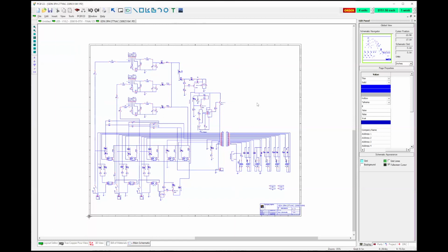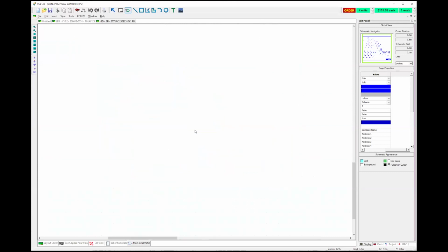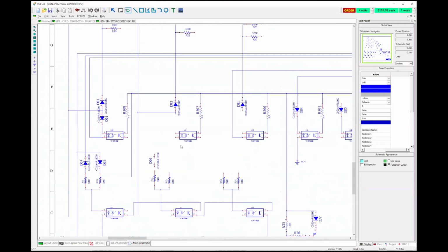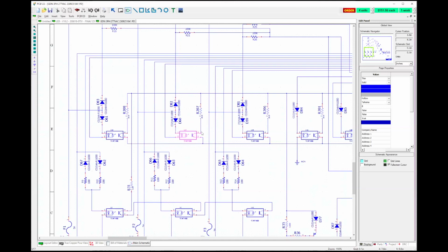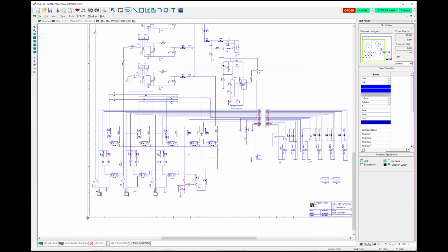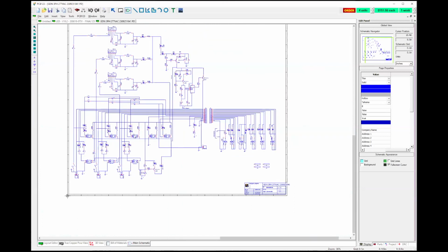Then I would go to the schematic, make a schematic symbol using, again, the same data sheet, and make the symbol so that it represents the part. And here's an example of a part that I had to make, this optocoupler. And then make sure that pin numbers are correct, the part orientation's right, and the interconnect between the two works as designed.